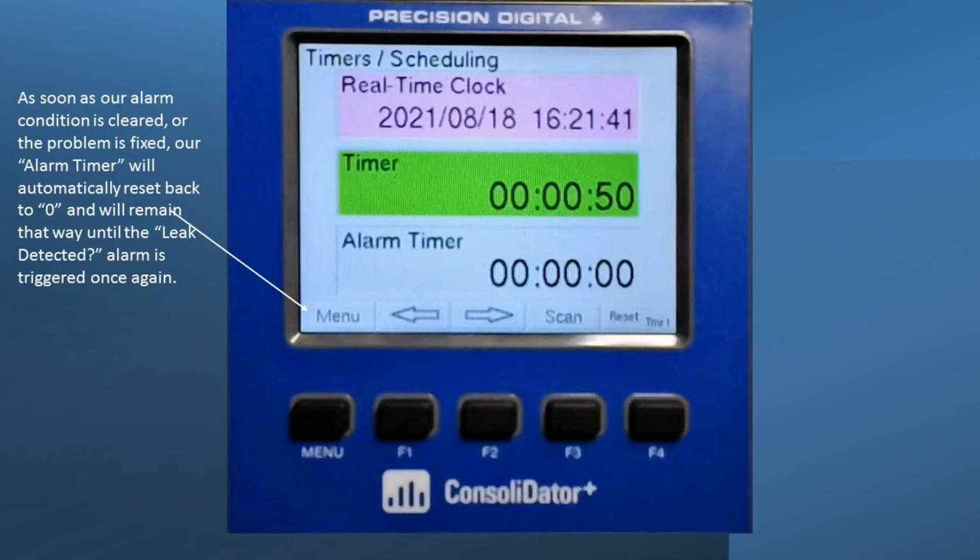Someone else asked, do we have an alarm history screen? Well, I have to think about that for a second. The answer is no. We don't have a screen you can go to that'll show you all of your alarms or whatnot. But as I mentioned in the last part of the last slide, if you wanted to, you could data log these things. So when an alarm is triggered, we could make that be the trigger for data log. And so it's not something that comes standard on the unit, but we can do a history of alarms in a roundabout way. So hopefully that answers your question.